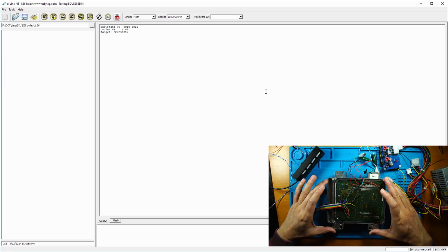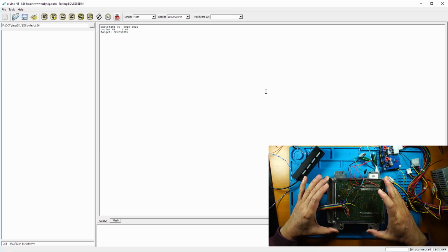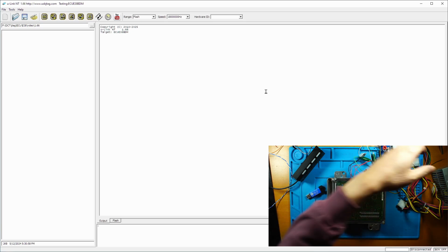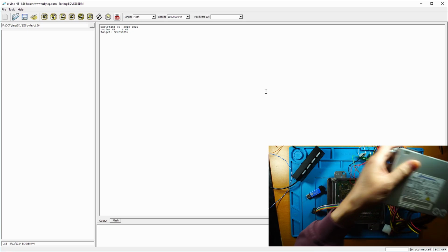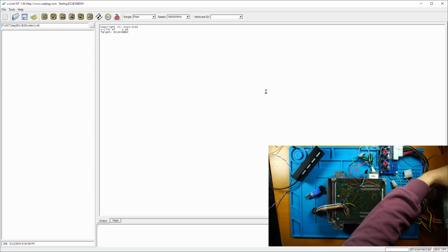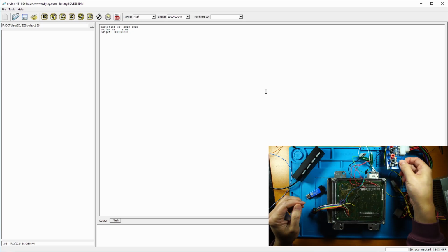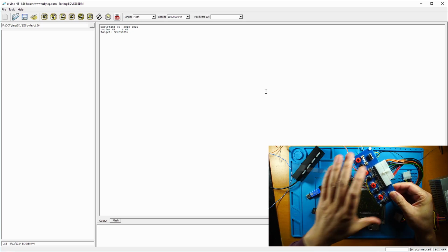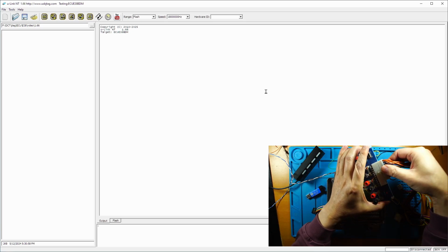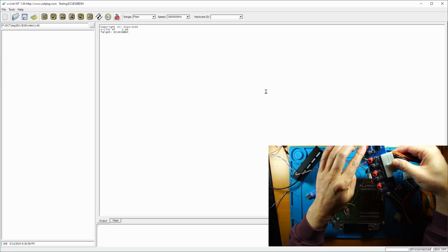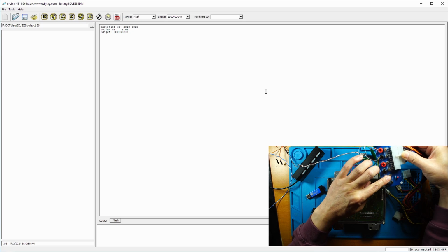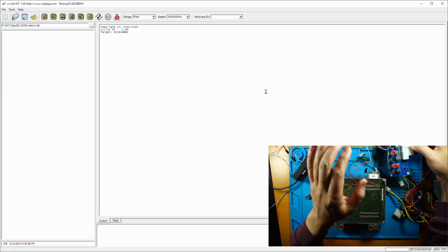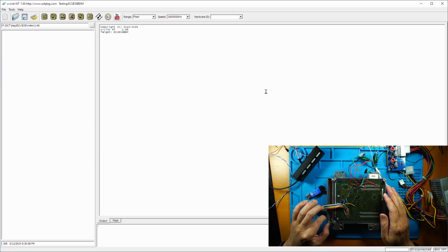It's very sensitive for the ECU to have proper power. Some 1 amp power supplies will not work. I'm using a modified PC power supply. So this is my PC power supply. It has its power switch. And I also purchased this adapter so I can plug this PC power into here, and then I get negative 12 volt, positive 12 volt, and 5 volt, and 3.3 volt, and the ground. This setup works very well for the ECUs.